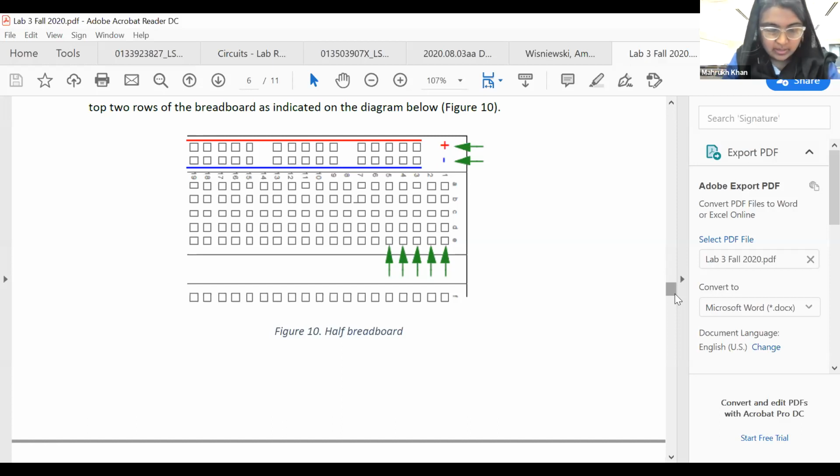Then you need to take a little portion of insulation off to expose the bare wire. From the two sides, using pliers, you should strip the wires like this. Can you see that? Is it clear? Can you do that? Of which gauge wire?